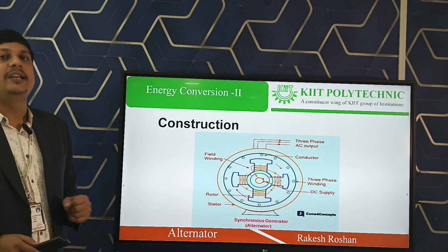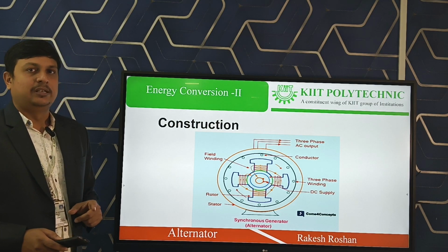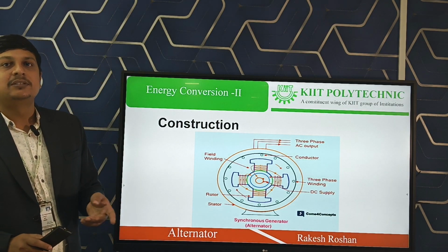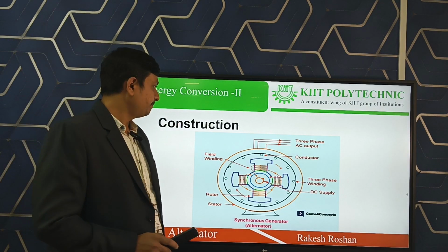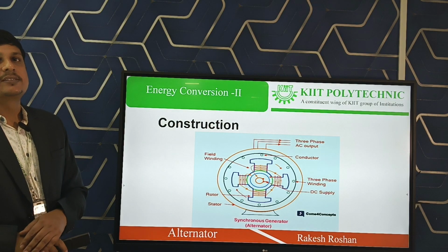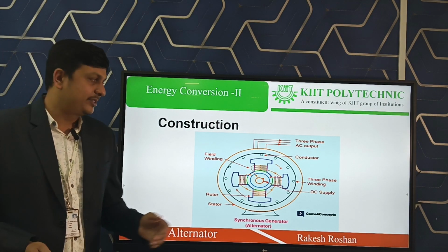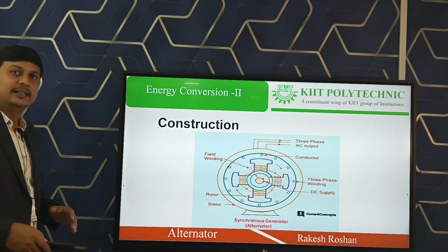If unbalanced loading occurs in alternators, a circulating current flows in the armature winding, and that is suppressed into the ground through the neutral. Also, it is helpful to eliminate third harmonics. So this is the advantage of your star connected armature winding.